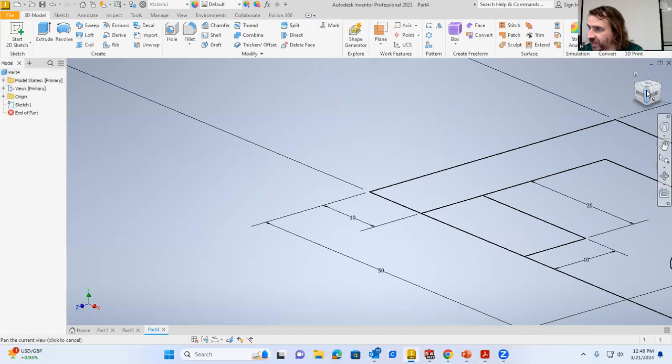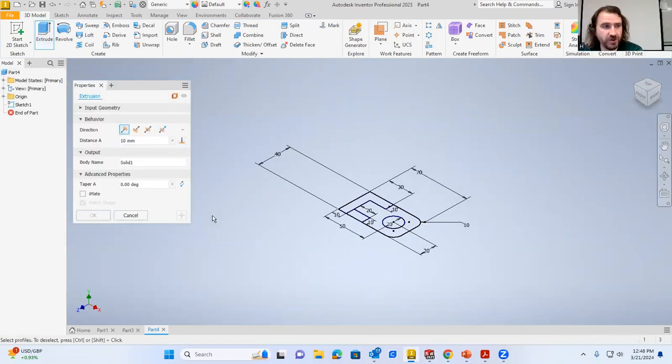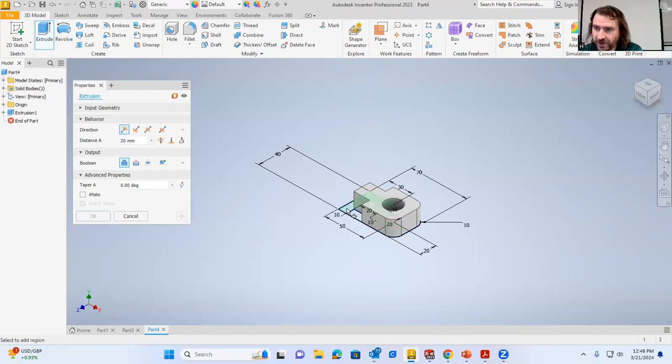We can finish this sketch, and we're going to extrude this. This feature here gets extruded 20 millimeters. This is the shorter one of these 3 different profiles. And again, we want to leave the profile of the circle unselected. We don't want to click on that circle, because then it's going to fill it in. It's not going to be a hole. So then we'll hit the plus sign again. That little feature is very nice.